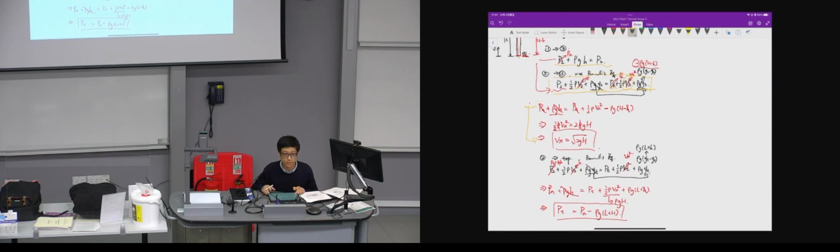Wait, so the beginning Bernoulli equation is PA plus half rho 0 squared plus rho g 0 is equal to PA plus half rho Vx squared plus rho gh. Not really. Sorry, what do you mean by very initial? Which two points are you comparing? 1 and 3 are my initial points. Okay, so if you compare 1 and 3, at point 1 you have 0 velocity, and so that will be half.